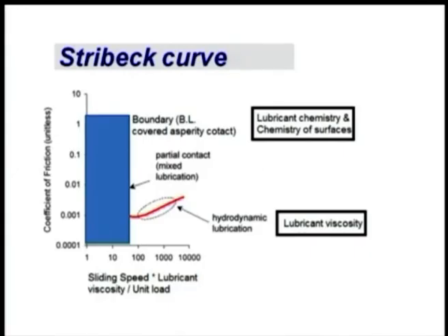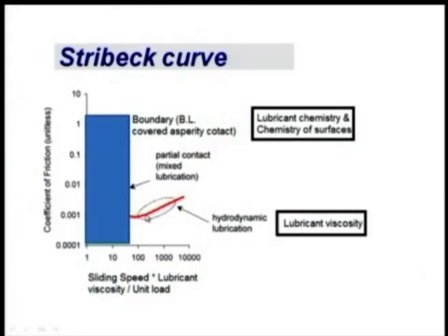Now, because of the heat, temperature will increase, and because of the increase in temperature, separation between molecules will increase. That is going to cause a lesser viscosity. That means, if we started at a point here, it will decrease. Because of lesser viscosity, bearing number will decrease and then coefficient of friction will decrease. As the coefficient of friction is decreasing, naturally heat generation will decrease. That is why the heat generation will be decreasing, that will lower the temperature.